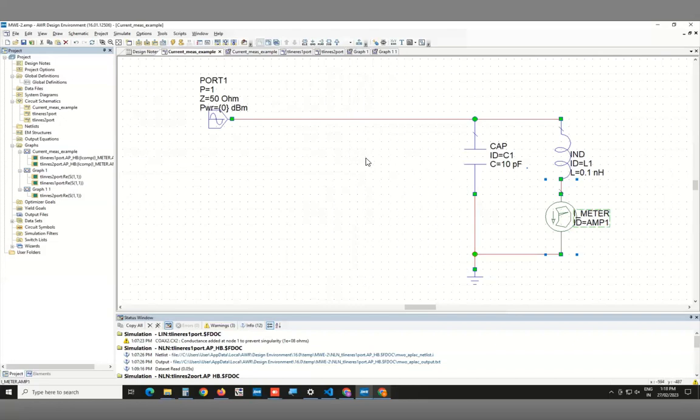The model which you understand is the simple LCR circuit, because for that you have a formula for Q. So you say, okay, can I now make this look like an effective parallel capacitor? Because then I can just add that capacitor to this and I know that the resonant frequency has shifted. When you do that calculation, it turns out that the capacitance value is the same value as what you had put in, but now it comes in parallel and adds to this capacitance, shifting the frequency lower.